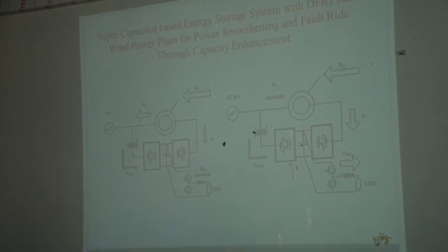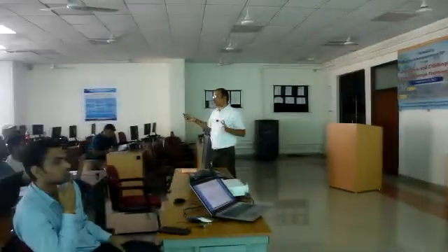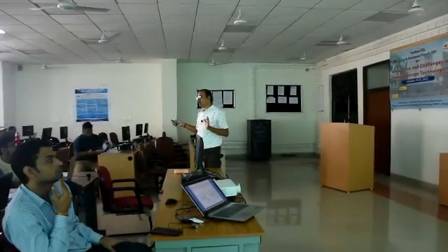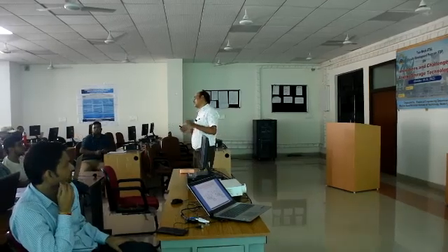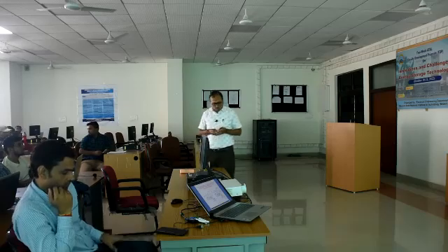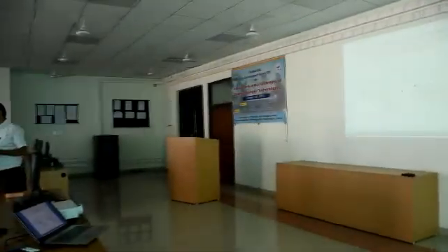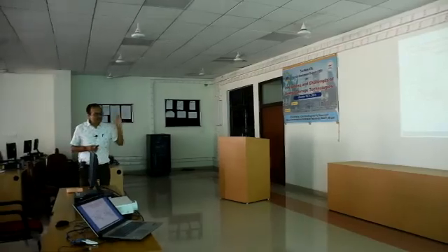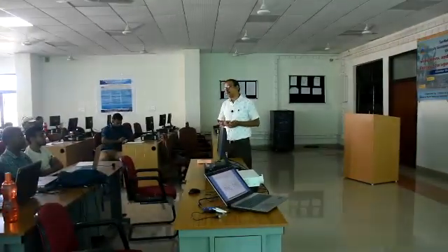Because if you are connecting and disconnecting the system, there are a lot of disturbances if you remove the systems from your main grid. You will face a lot of challenges. So basically, in this case, we are trying to increase the fault ride-through capacity, the fault ride-through enhancement. The same application, the same storage systems, are used for the fault time ride-through enhancement.